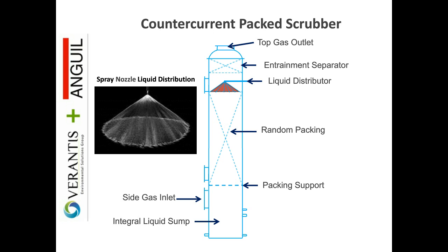So a lot of times you'll see an arrangement like we have pictured here with a full cone, full coverage spray pattern out of a spray nozzle, just to make sure that we get very even coverage across the top. When you have coverage problems, issues with liquid distribution throughout the bed, you can end up with performance issues.